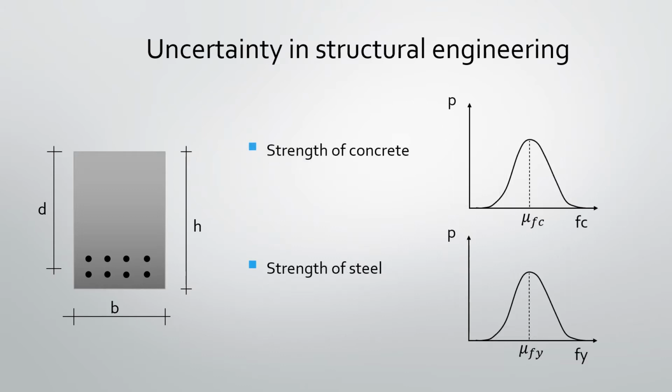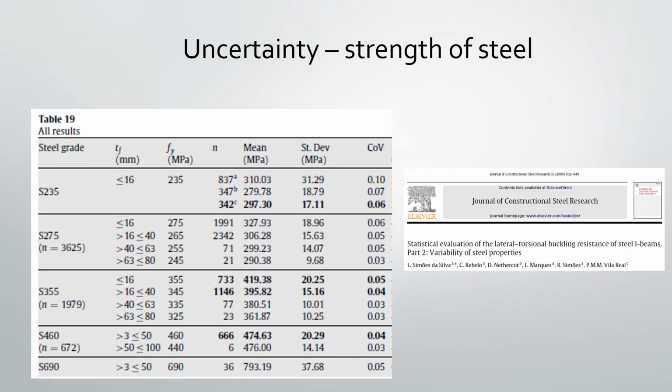When the compressive strength of concrete, or yield strength of steel, are tested in a laboratory, the results normally have a significant variation, similar to what we saw in the experiment with the staples. The data from such tests often follows a log-normal distribution. Here are examples of yield stress measured experimentally.